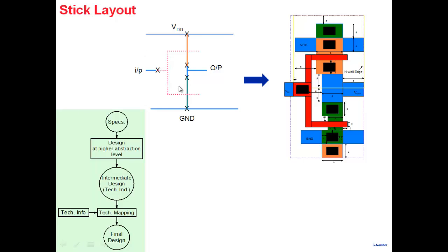And don't look at this intermediate step. So whatever circuit is given, you jump straight to this particular part here. And if you try to jump to this particular part, maybe your thinking will be, as I said, burdened by all the rules, information and all that. So this stage where you're sketching the stick layout will help you in your ability to come up with different ideas. So even if, let's say, there's no CAD tool, you still have to do it. This intermediate stage will help you conceptualize your layout better, and then you go ahead and do it. Okay. So stick layouts have that particular advantage.